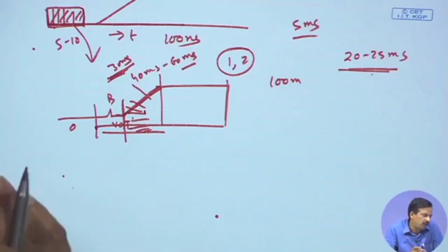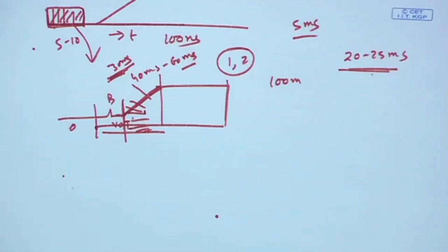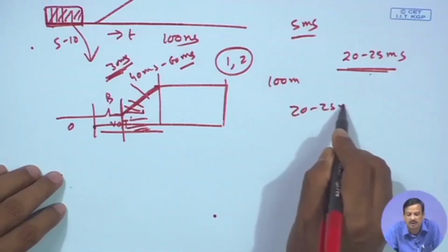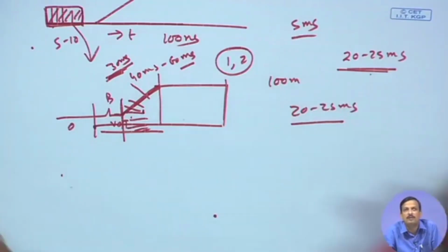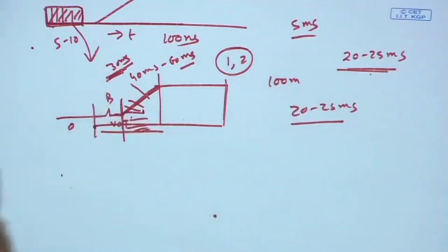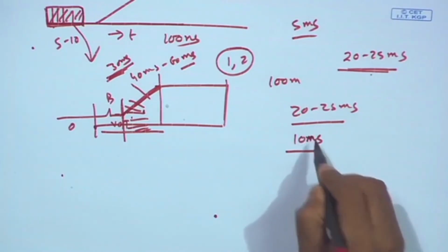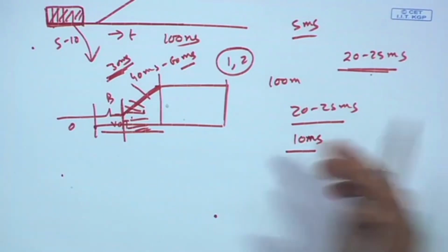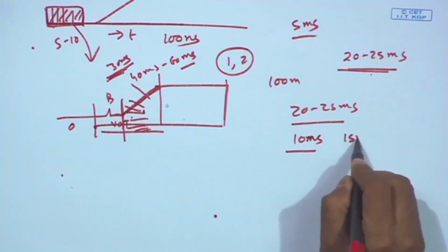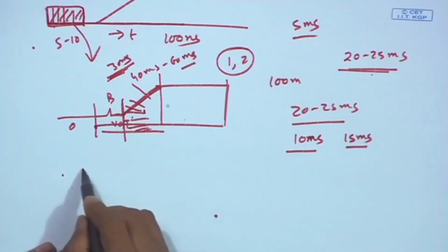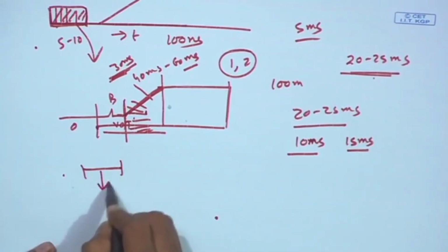So, that is why in the whole processing of speech we use 20 to 25 millisecond as the window length and shift the frame by 10 millisecond, so that I get 100 frames per second. Okay. You can shift it 15 millisecond also, but what will happen is for every 15 millisecond I get a vector.